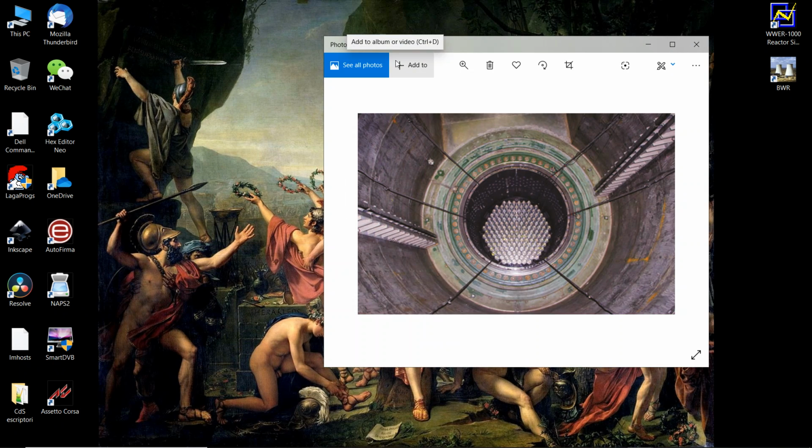Hello reactor enthusiasts, this is the second part video for the numerical background modeling of the WWER-1000 simulator. In the previous video I tried to prove my hypothesis, which is that the model doesn't take into account boiling in the primary water. After fighting with a lot of rod withdrawal, insertion and boron concentration, I could not prove my point because I didn't have enough available reactivity left in the rods that were not inserted, and I could not conclude anything in that video.